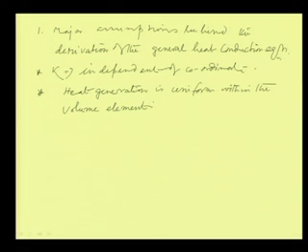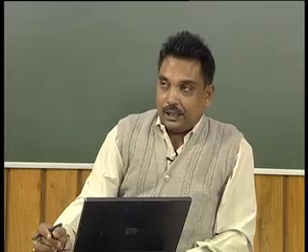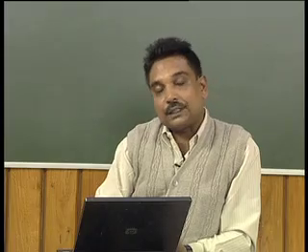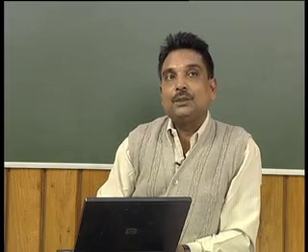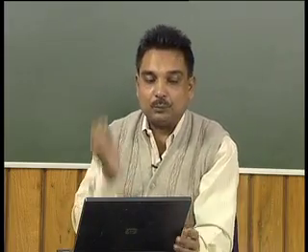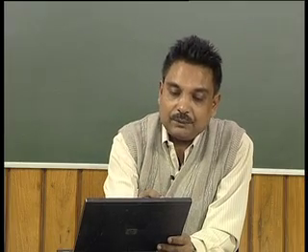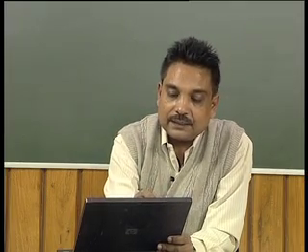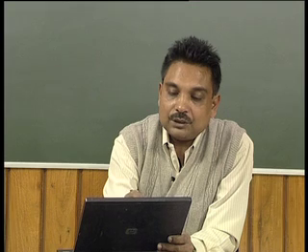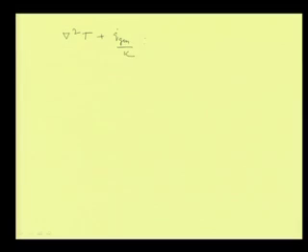Okay. Now, we will see some other problems. Let us suppose that we have this equation of general conduction equation, the general form we have found out. What is the general form of equation we have found? We have found the general form equation, del square T plus q dot generation by k is equal to 1 by alpha del T by del t.